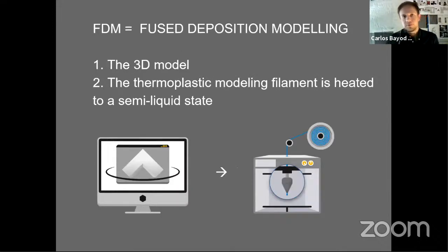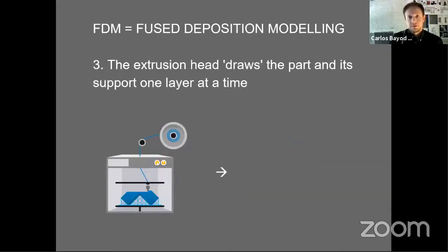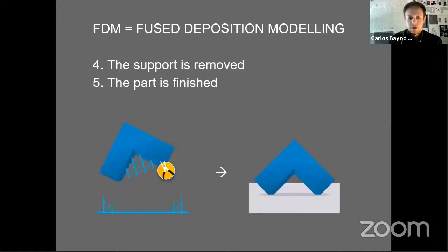So just a few diagrams of how this technology specifically works. Once you have your 3D model that you want to generate, any design, any 3D shape that you want, this machine is understanding the piece as a stacking of layers. You are building, as if you were drawing in space, the shape with this filament that, because of the heat, becomes liquid, and then it can become solid again just after a few seconds. What you obtain is a shape that corresponds exactly to the 3D model that you have in your computer.